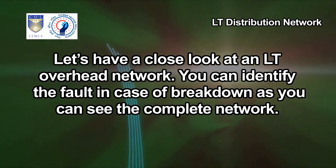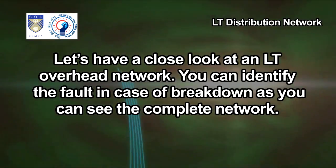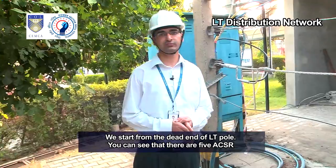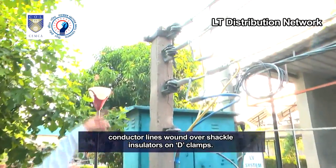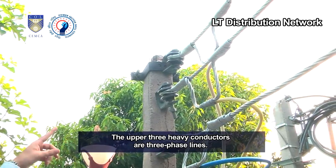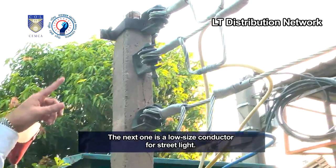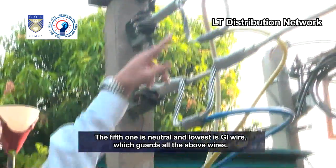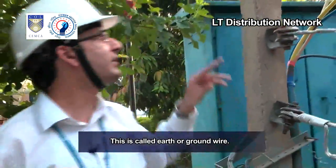Let's have a close look at an LT overhead network. You can identify the fault in case of breakdown as you can see the complete network. We start from the dead end of LT pole. You can see that there are 5 ACSR conductor lines wound over shackle insulators on D clamps. The upper 3 heavy conductors are 3-phase lines. The next one is a low-size conductor for street light. The 5th one is neutral and lowest is GI wire, which guards all the above wires. This is called earth or ground wire.